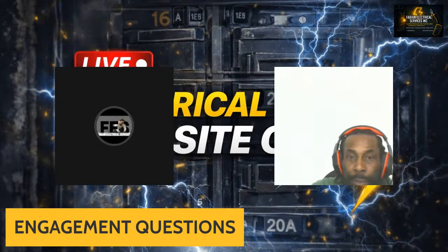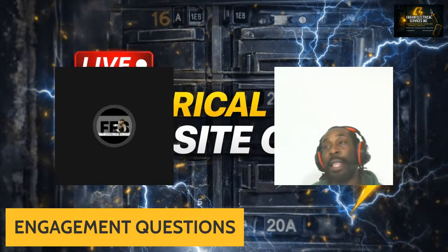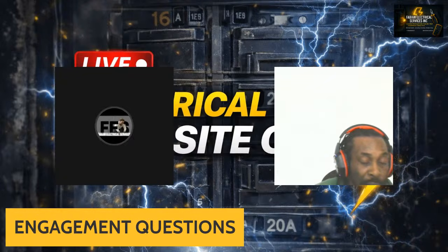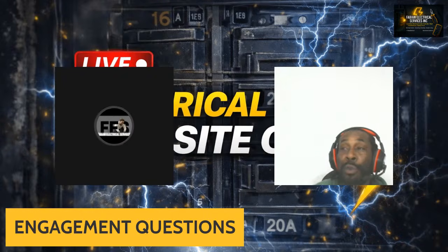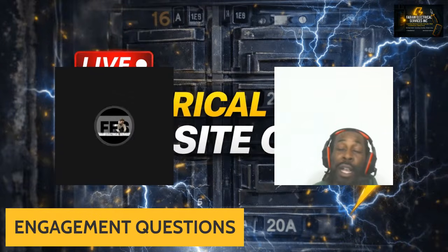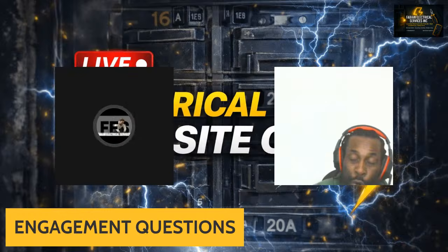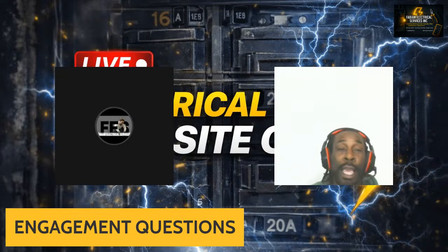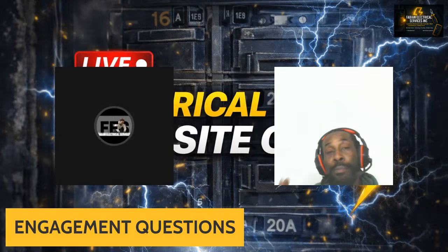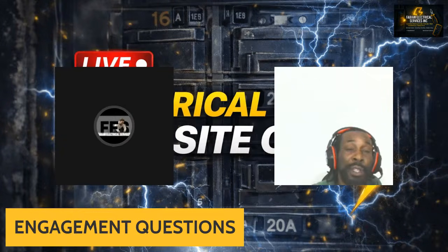So again, what that was, was me troubleshooting in real life, people, and not walking back and forth to find the circuit. You're going to mostly have to troubleshoot when the panel is not labeled correctly, or when your circuit is not sized accordingly, the 80% rule, or when you're not using the proper breaker for the proper size wire.